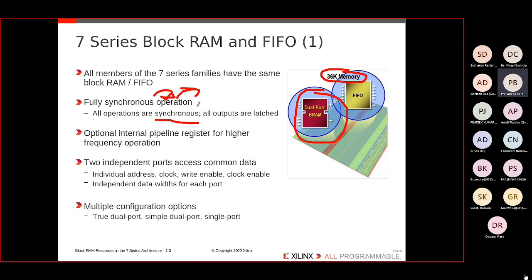So whenever I am writing RTL code where my read and write are synchronous, that is, happening on the clock edge, the tool will understand that I'm inferring a block memory. That's why it's called block memory. One block of memory is given. But what is the disadvantage? If I'm using even a 1-bit memory, it will take a minimum of 18 kilobits of memory. Only 1 bit will be used, and the other 18 kilobits of memory will be wasted. So that's why it is recommended to use block memory only for bigger memory implementations.